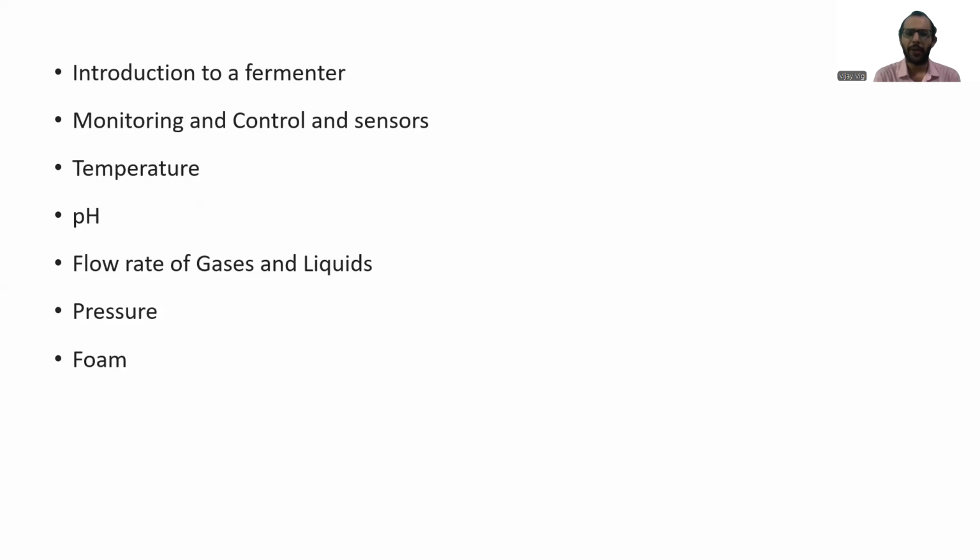Foaming occurs during a fermentation and it has to be controlled because it will massively affect the fermentation process, sometimes resulting in a loss of a fermentation process. So antifoams have to be added. Monitoring and control of foam is highly significant.